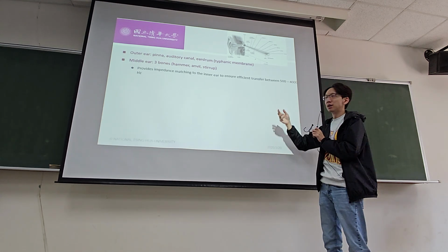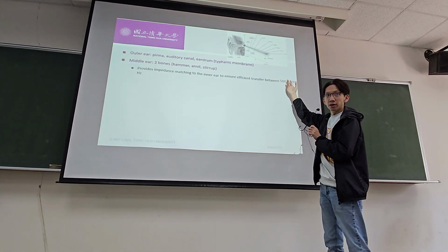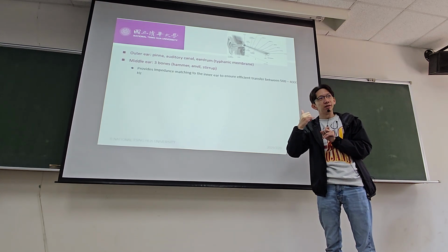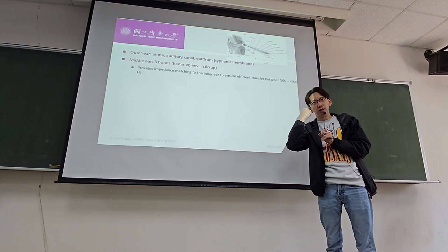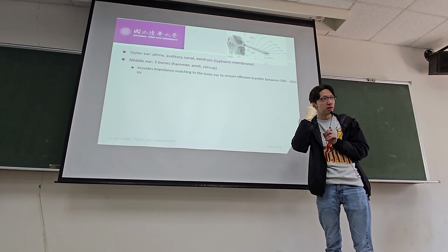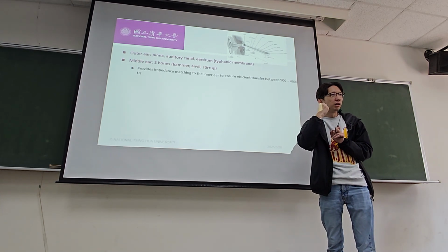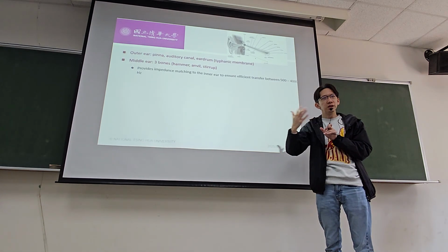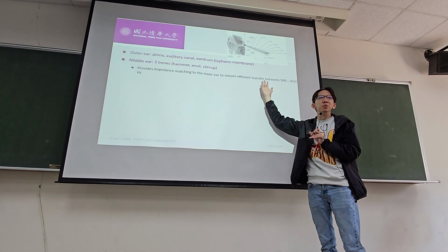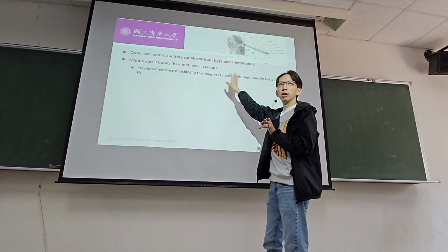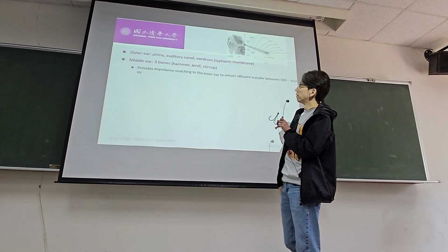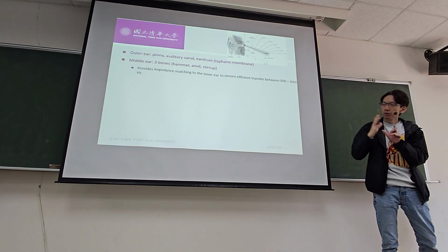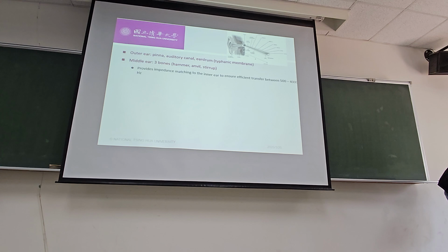Everybody speaks in this particular hertz range, and that's also why, when we designed the first landline wired phone, you pick up the phone and talk, not the cell phone, that thing has an 8 kilohertz sampling rate, so the Nyquist rate is 4,000 hertz. Similarly, the whole design is because we somehow know how humans perceive stuff. So the bones provide impedance matching to make sure the energy between 500 and 4,000 hertz is properly transferred.